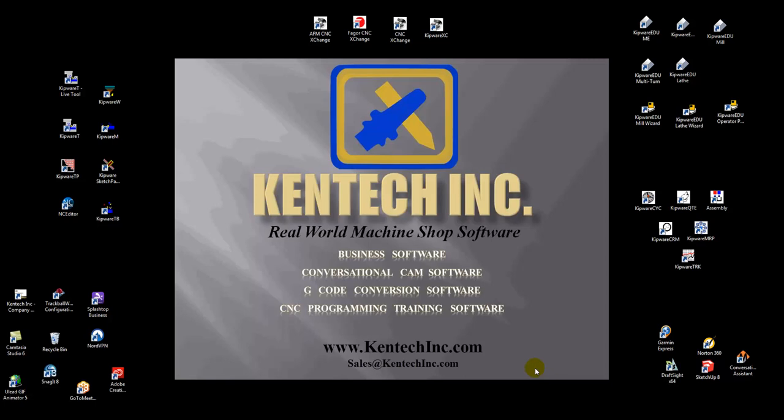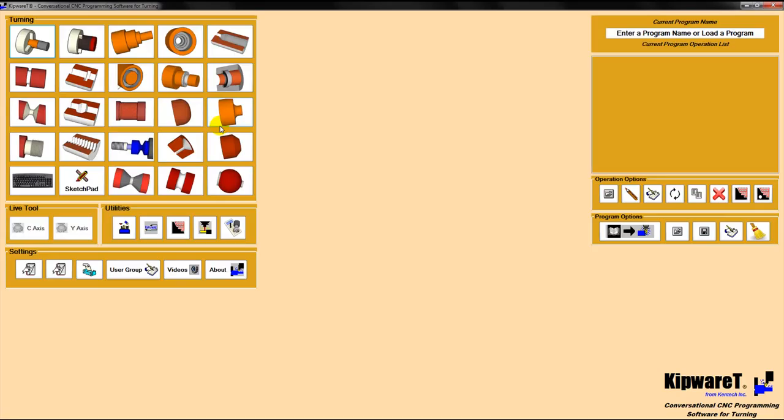This portion of the video is going to take into account creating the program using Kipware Conversational. And again, one of the big differences is we don't have to create a drawing. So we're going to go right into creating the G-code. So we've eliminated the 10 minutes or so that it took us to create the drawing in Fusion 360. The design is basically we're going to choose operations from the conversational screens. We're going to create cycles, put those cycles up in the tree, and then create a program that's going to link all the cycles together, one big program that I can send to the machine.